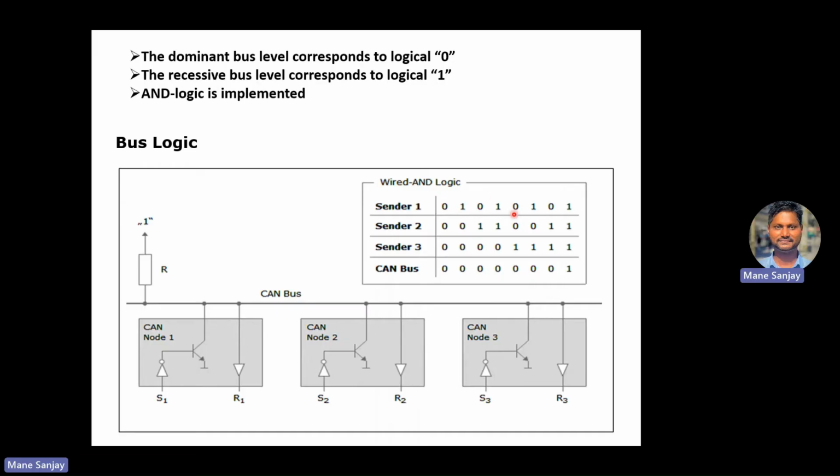So if I decode this value, it comes as 0101, that means 4-2-1, so this is 5, right? And again, some value, this is 5. So 55. And here, some value, this is another value. So this is a logically higher numerical value compared to this. That way, if you see in the CAN network, if one of the identifier values is lesser than the others, then the lesser wins the arbitration. That's what is written here.